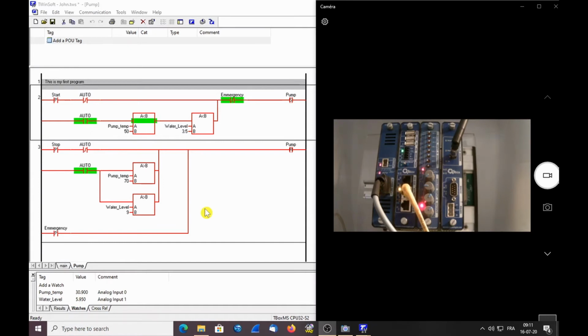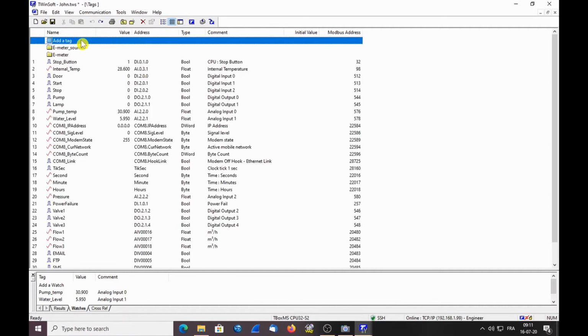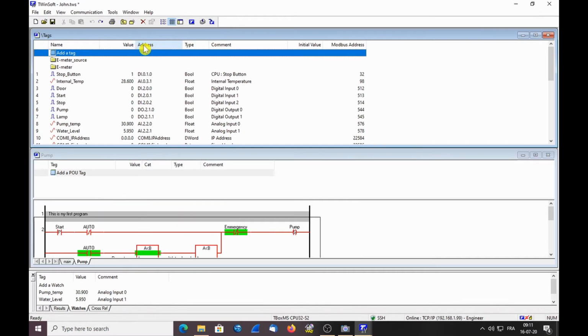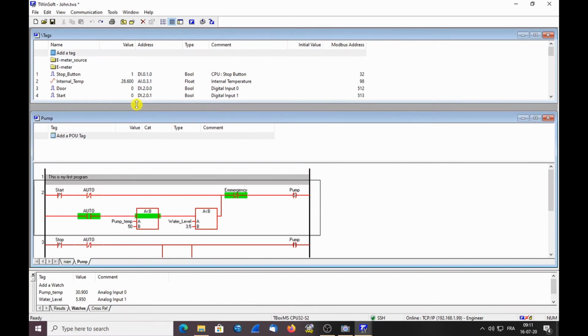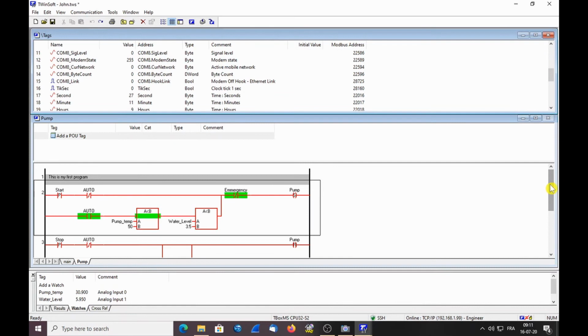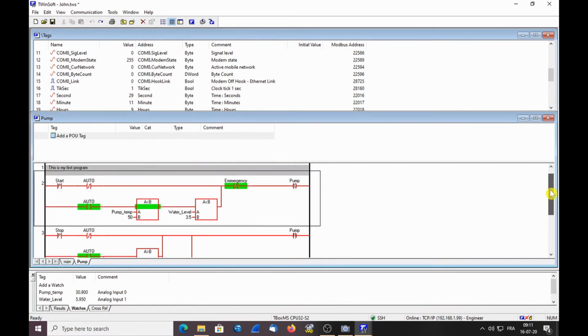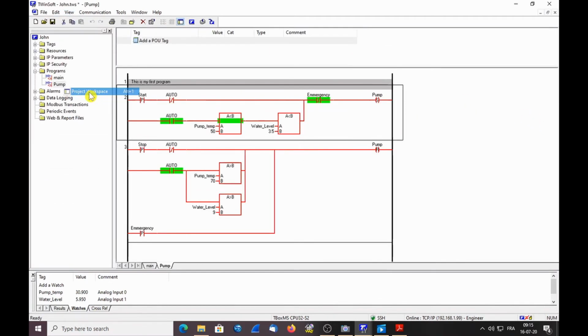So I have at the same time visibility on my process and on the values of tag. Another possibility of displaying tags is displaying multiple windows. I have a window menu, I can make a new window, I select my list of tags and then I can display the windows horizontally and I see my list of tags at the same time as my process, and I can change the size of the window. To continue, let's maximize this window and display back our project workspace.